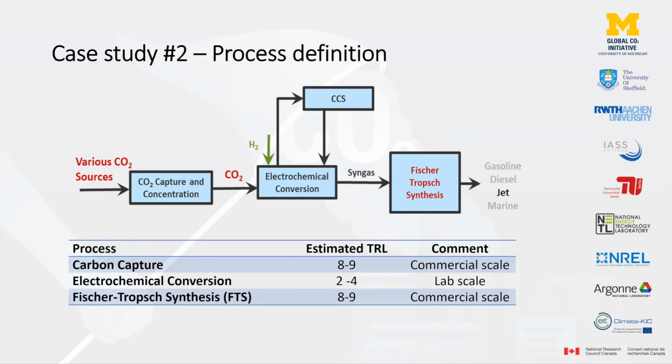Those hydrocarbons can be fractionated into gasoline, diesel, and jet fuel. If you study the Fischer-Tropsch synthesis kinetics, you can actually target more of the jet range hydrocarbons by changing some of the catalyst severities and loadings.